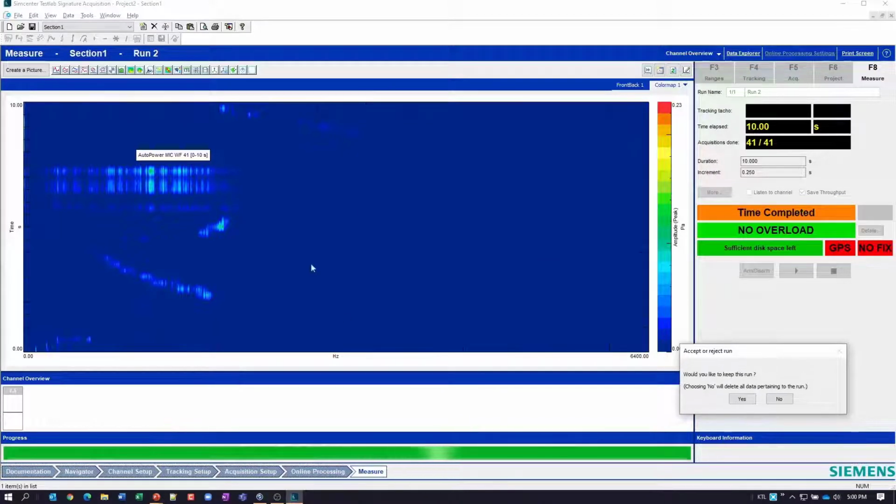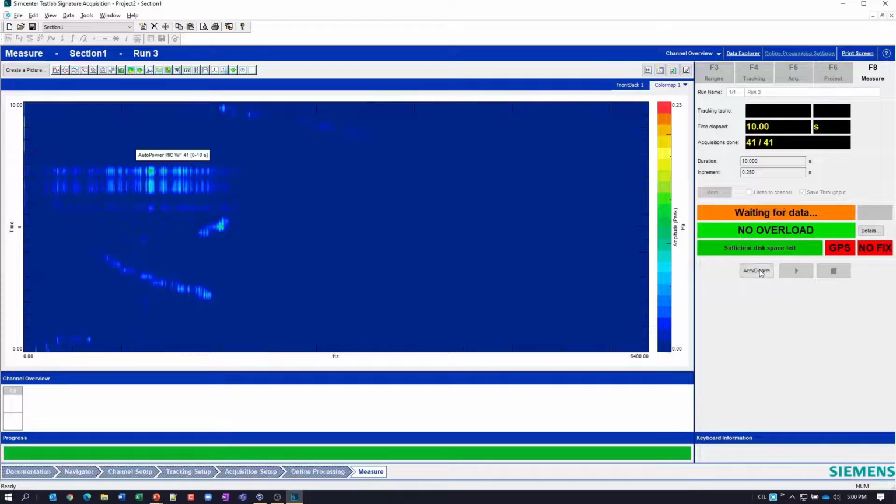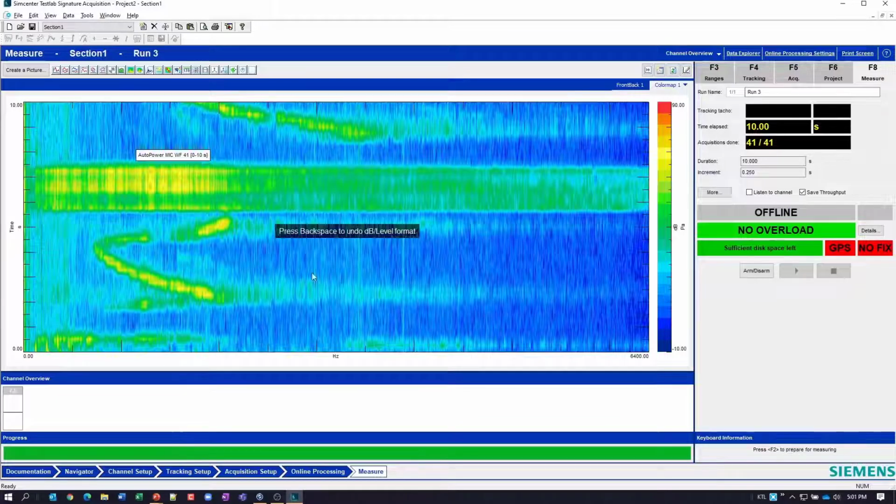Okay, so there is our frequency spectrum versus time. You get a quarter second, a half a hertz resolution for each frequency spectrum, and this is what it looks like. And I can say yes, and I'm afraid that's going to disappear. No, it won't. So I'll disarm here, and I'll go ahead and put this into decibels. It'll make it look a little bit more interesting. And so you see the whistle frequency changing with respect to time. You see my claps, which are sort of broadband in frequency. And I have this sort of nice tracked measurement.